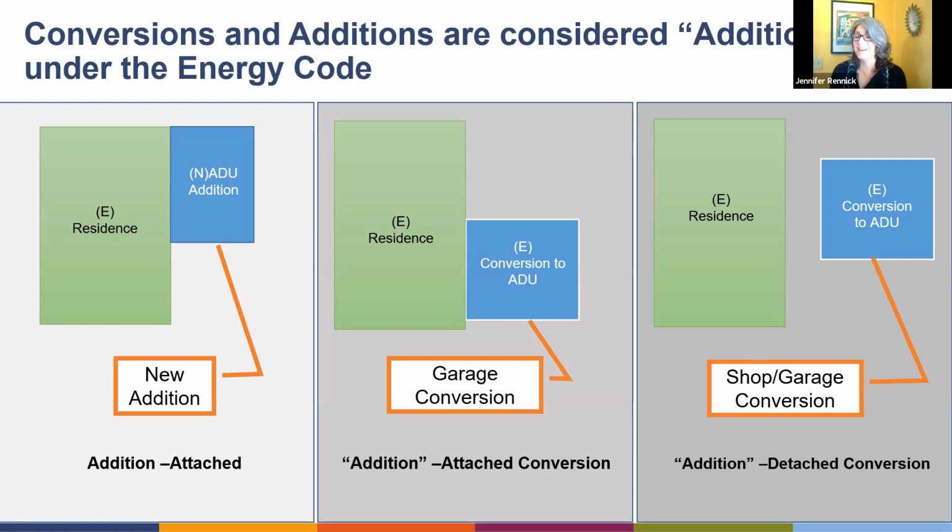But if you're wanting something small like that, we've got some projects now that are complying even with a PTAC unit, depending on the situation. It improved the performance to move to a wall unit under the window, a PTAC, and it's a heat pump and it provides heating and cooling. And we were able to get rid of the gas wall heaters altogether.